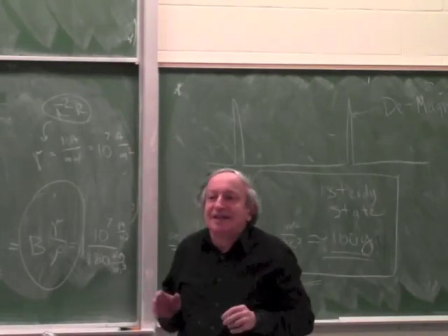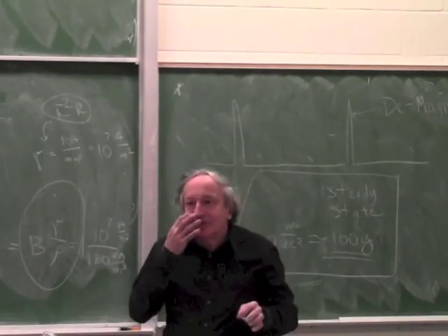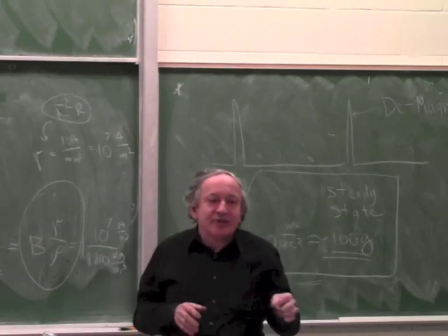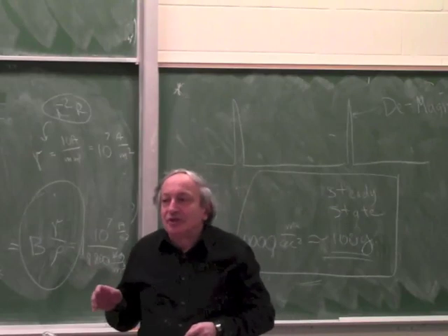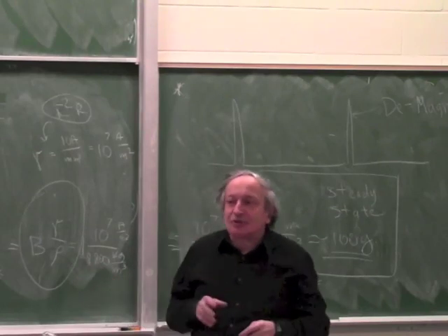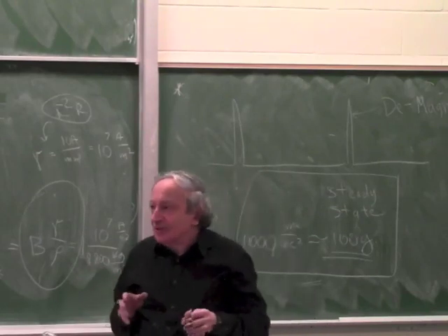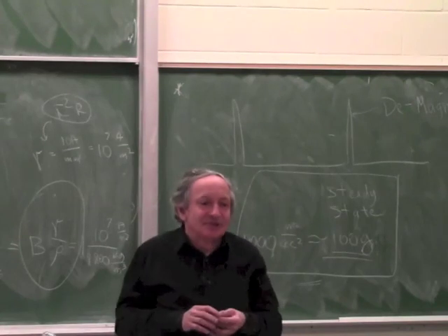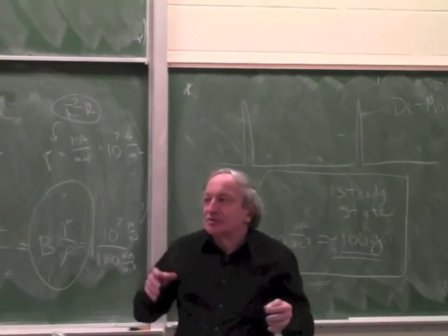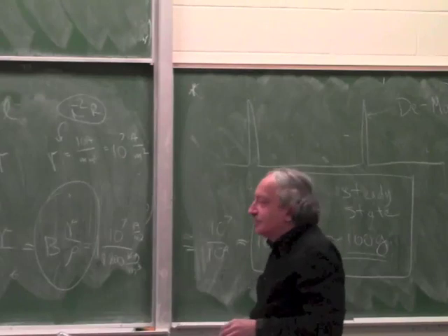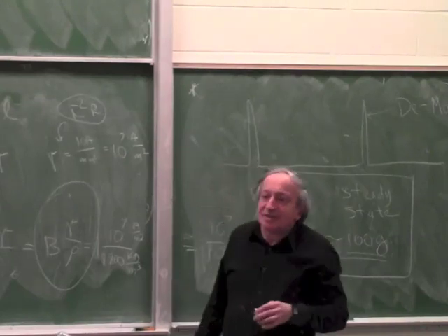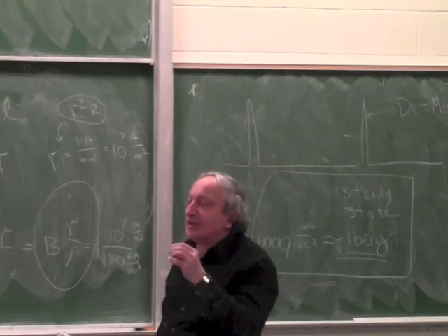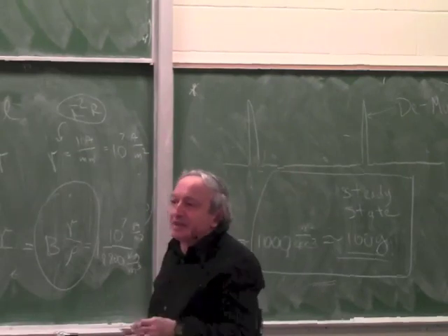It only conducts 10% better than copper. As you know, different copper alloys conduct differently, but there is a standard copper alloy used for making coils. It's called oxygen-free copper, and this copper conducts 90% of silver. So all the coils you see are made from this copper. Strangely enough in metals, just a teeny bit of alloying element kills electrical conductivity